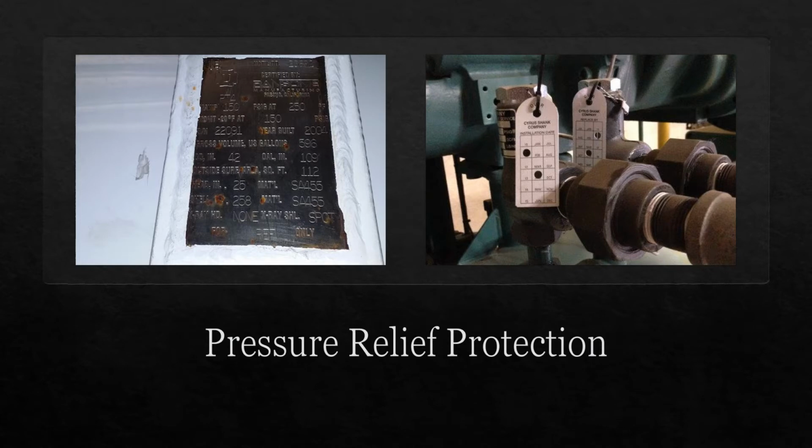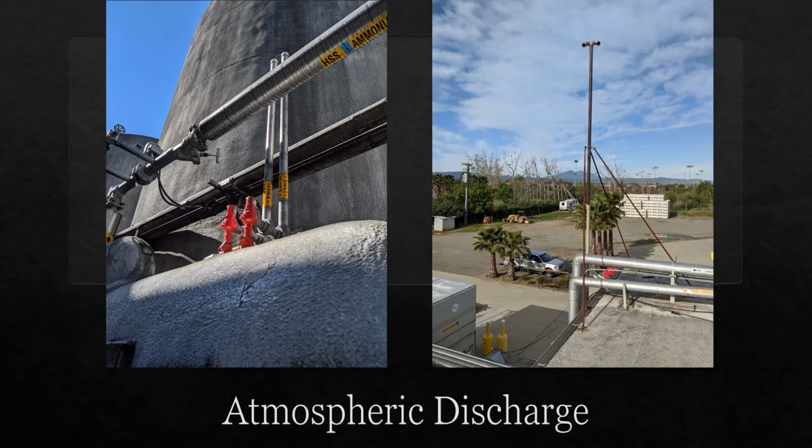Standard 9 requires that ASME vessels and heat exchangers be protected from overpressure with an ASME relief device. While Standard 9 does not include prescriptive requirements for sizing relief valves or termination piping, it does mirror Standard 2 in requiring that relief valves terminate to atmosphere at least 15 feet above grade and 20 feet from a window, ventilation intake, or exit door.